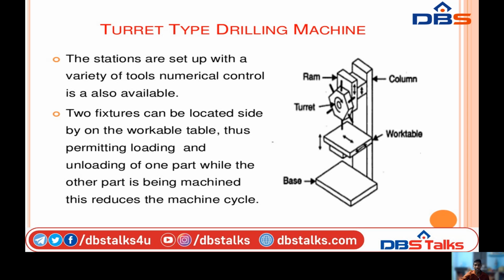That means what he is saying in the turret type drilling machine is that two fixtures are located side by side on the work table. In the middle, I am showing the work table here by the arrowhead. In this, we are fixing the fixtures side by side. This permits the loading and unloading of one part, and while one part is being unloaded and loaded, the other part is being machined. This reduces the machine time. That means by using the turret type drilling machine, we can reduce the idle time of the machine.